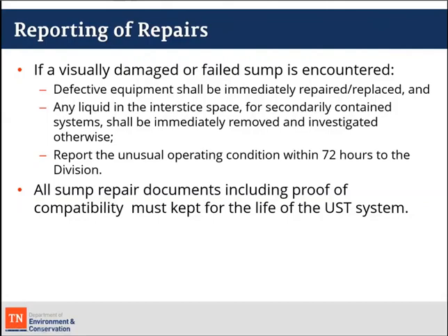Again, this last point is crucial: your repair documents must include proof of compatibility. Not just that you repaired a sump, you have to show how you repaired the sump and also that the sump after the repair was tight. And those documents must be kept for the life of the UST system.